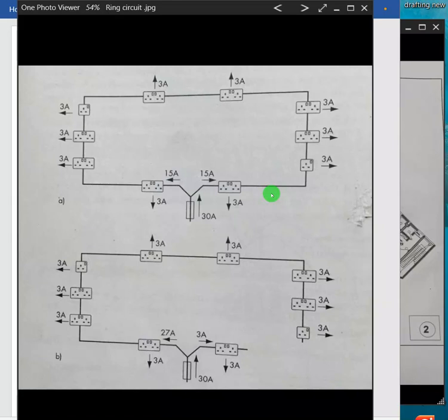All right. Okay, so that is the requirement for a ring circuit. The advantage of a ring circuit is that whenever we have an open circuit along the ring, the current is going to be complete. The whole entire socket point is going to have power because, supposing I have a breakage here, this cable will supply, the other second cable will supply the whole of this part.